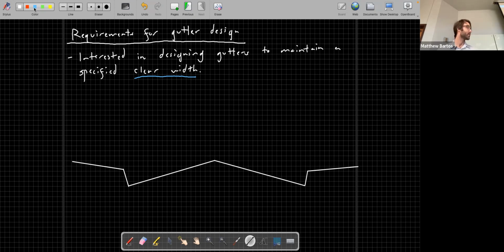Okay, so this is a roadway. Let's say that this is a residential collector. It has a kind of a regulated width. So let's go ahead and draw the dimensions on here. It is 24 feet wide with 12 feet on each side.